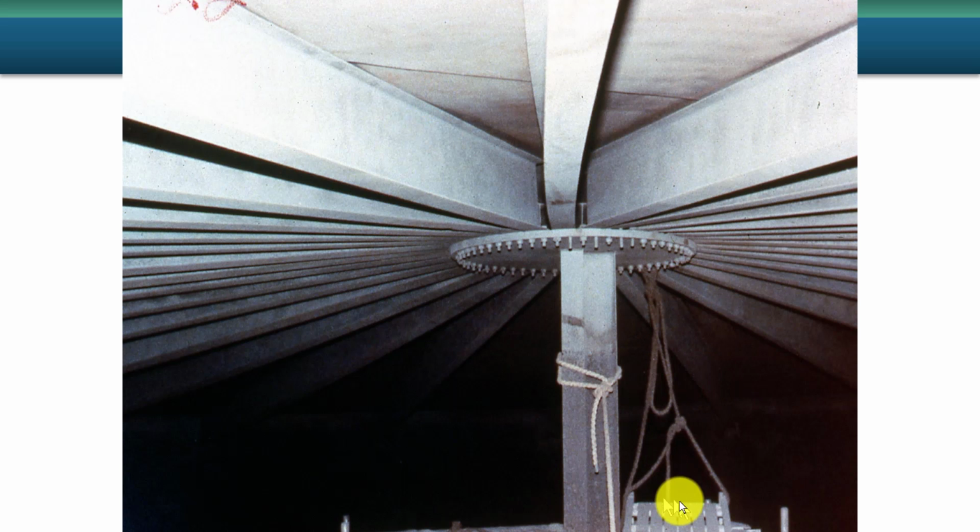You can see that this inspector used a bosun's chair and fall protection to access this area. No, this is not a romantic starlit night. This is a view of the storage tank roof with 1,000,000 points of light caused by corrosion coming in from the outside. It's basically paper thin.